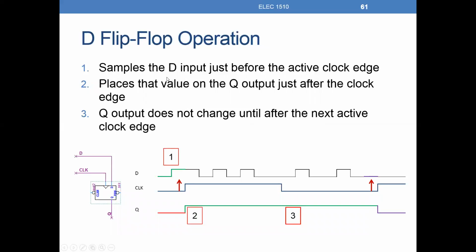Here's how the flip-flop then operates. Let's look, starting on the left, this is time t equals 0. D happens to be a 0. I'm saying that Q is a 0 at this point in time. Here is the clock signal. At this particular point in time, the clock transitions from low to high. So this arrow indicates the rising edge. It's rising from 0 to 1. Notice here, this is our symbol. This is a rising edge triggered flip-flop. There's no inversion here on the clock. So at that point, the output Q transitions to whatever is on the input, D. And right here at this point in time, D happens to be a 1, so notice Q becomes a 1.